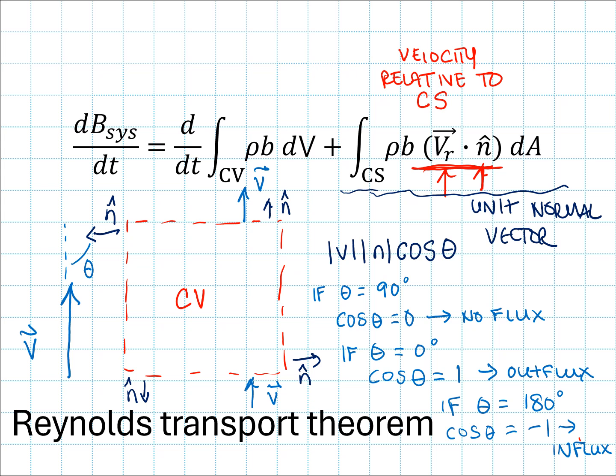So this is why we have the dot product of velocity, is to indicate, first of all, the component of that velocity vector that's contributing to the mass flux across the control volume, across the control surface, but it's also to keep track of the directionality, right? Because this third term in our Reynolds Transport Theorem, it's specific about directionality. It's the amount of mass, energy, or momentum that's leaving the control volume, so mass, energy, momentum out, minus mass, energy, or momentum coming in. So we have to really keep track of which direction that mass, energy, or momentum is flowing at any given time.